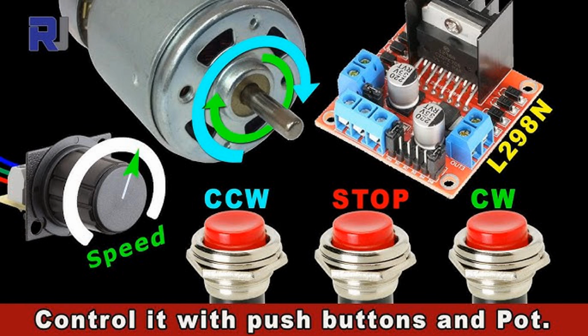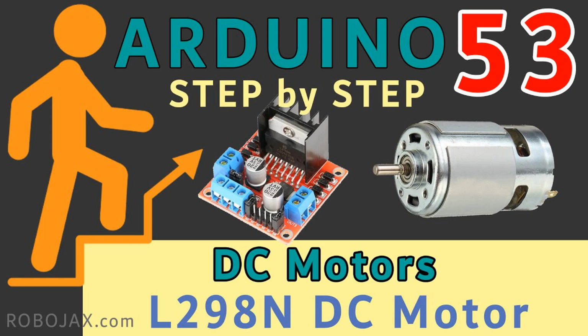Advantages: simpler design, often less costly, and lower power consumption since only half of the coil is energized at any given time. Disadvantages: provides lower torque compared to bipolar drivers. Applications: common in applications requiring less torque and lower precision. Examples: ULN2003, L298.